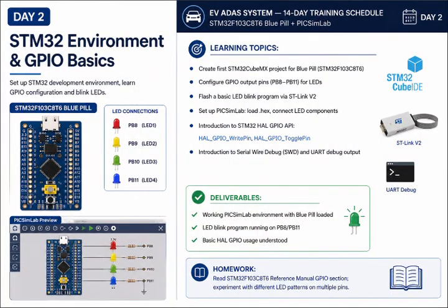Coming to day 2, I learned how to set up the STM32 development environment using STM32CubeIDE and CubeMX. I configured GPIO pins for LED control, understood STM32 HAL functions such as HAL_GPIO_WritePin and HAL_GPIO_TogglePin, flashed the firmware using ST-Link and simulated the hardware in Proteus Lab. This day helped me understand the basic workflow of STM32 programming.